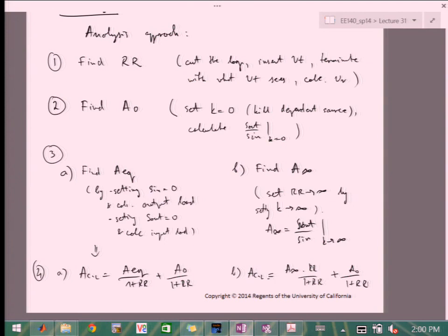But you'll pretty quickly see how involved it is, and you'll hopefully say, no, we don't want to go down that road. It goes along the lines of what I started showing you: shunt, series, series, et cetera. For each one of these types, you have to figure out the equivalent amplifier path and the equivalent feedback path. So it gets out of hand pretty quickly. That's why I'm showing you these return ratio methods, because in practice, they're a lot easier to deal with.